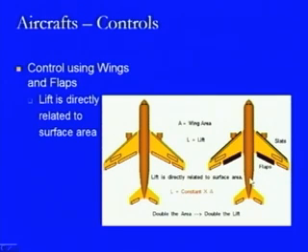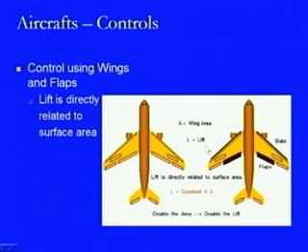So, what we do is that at the time of landing the pilot is not using the brakes so as to reduce the speed of the aircraft from something like 300 kilometers per hour to 90 kilometers per hour, at the time when it is going to take a turn from the runway and come to the taxiways. So, the speed which is being reduced in this portion from 300 to something like 100 kilometers per hour is done with the help of these flaps only, and the drag force which is generated by using the flaps. Only after that the pilot starts putting some brakes as and when they are required.